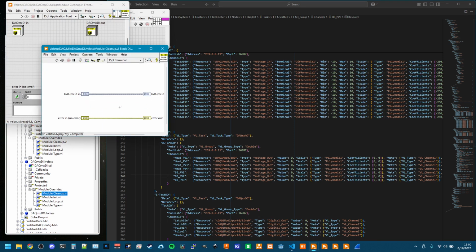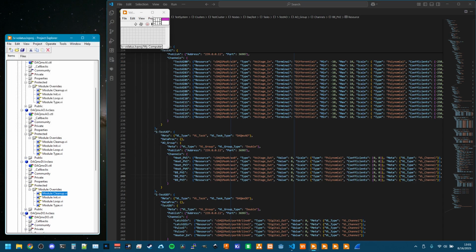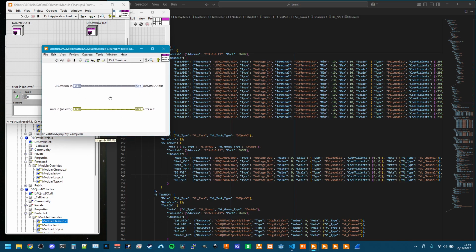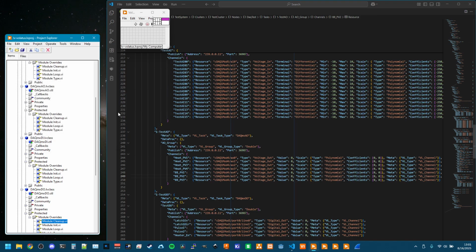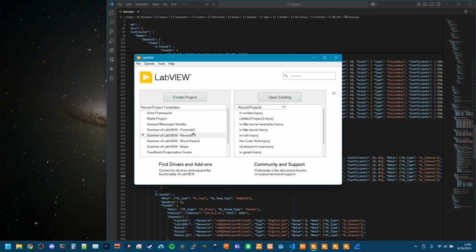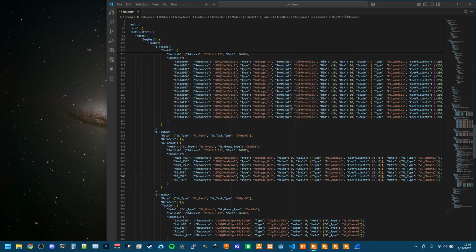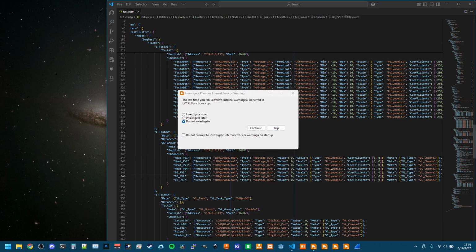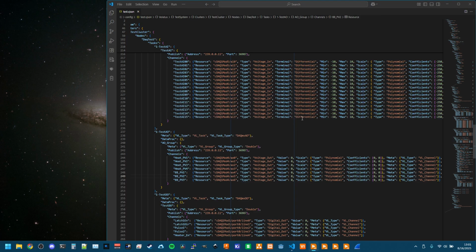I only did it on one of them. Must have been the one where I had an error like that before. Now that task does exist, and maybe somebody can let me know how to get it closed after the fact, but it exists, and until we unload the DAQmx DLL from memory, I do not know how to get rid of it. So I will close and reopen LabVIEW, and we will have to wait just a little bit longer.